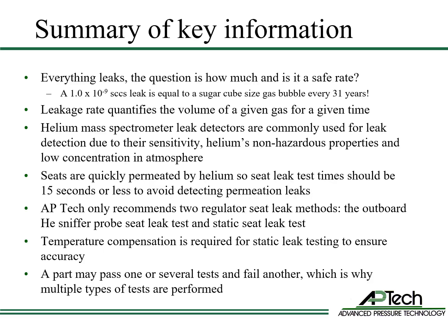Let's review a summary of the key information about leak detection. Everything leaks. The question is how much, and is it an acceptable and safe rate? A 10 to the minus 9 leak rate is equal to a sugar cube sized gas bubble every 31 years. Leakage rate quantifies the volume of a given gas for a given time.